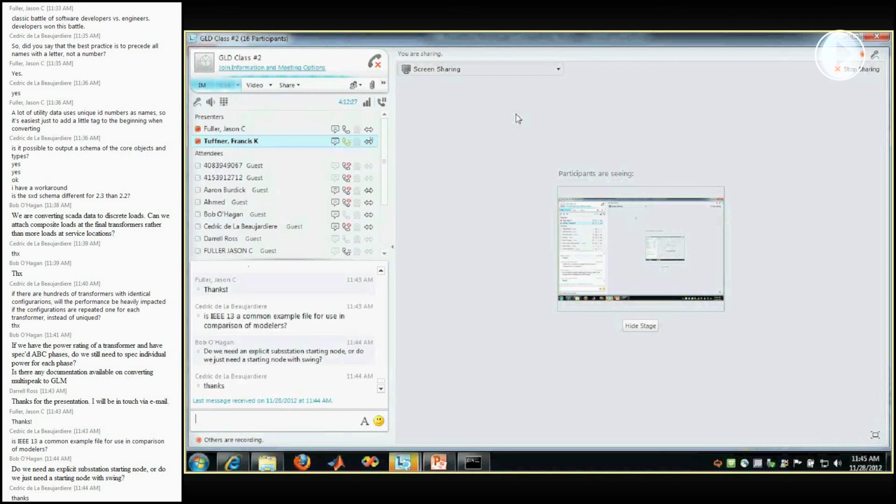The only caveat is one of the newer functionalities we have, interfacing the PowerFlow module with PowerWorld to do transmission and distribution level interactions. In that particular case, you do have to have a substation at the top of your feeder in order to interface with PowerWorld. But outside of that, as long as you have a swing node somewhere on the system and it's a node, load, or meter, it doesn't really care where it's at. It'll affect your solution, of course, if you set the bottommost load as your swing node and let the rest of the solution solve off of that. It'll give you some different results, but there's no real limitation on where you put the swing node. It doesn't have to be a substation. It can be anywhere else.